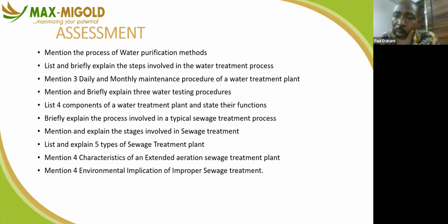They are treated separately. Sewage is separate because sewage is your wastewater that you have used in the facility. Your normal treatment plant is for water that is coming from the borehole. Your sewage can be treated to the level of drinking. It's possible. But most places where I've seen sewage in the country, it is being treated to be discharged to the public drain. People that don't have the money to build a sewage treatment plant venture into what we call a fat trap. They construct a stainless steel fat trap, and they do what we call a general cleaning, possibly a daily cleaning of the fat trap.